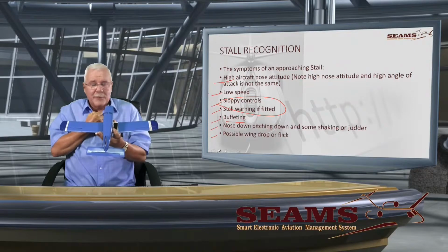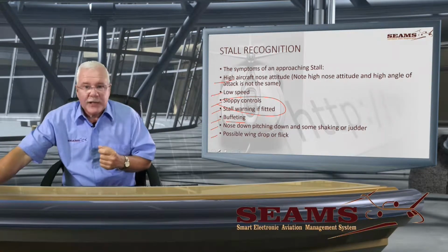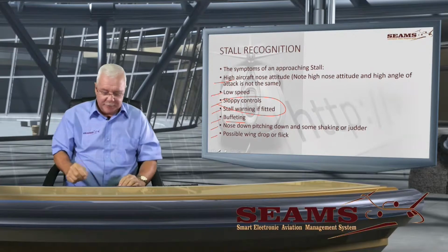You know, and some of the aircraft, when we keep it in the stall like that, like in the Seminole, 1,800 feet per minute rate of descent. Interesting stuff. All right, so be careful of that. You need height. You need to understand what you're busy doing.